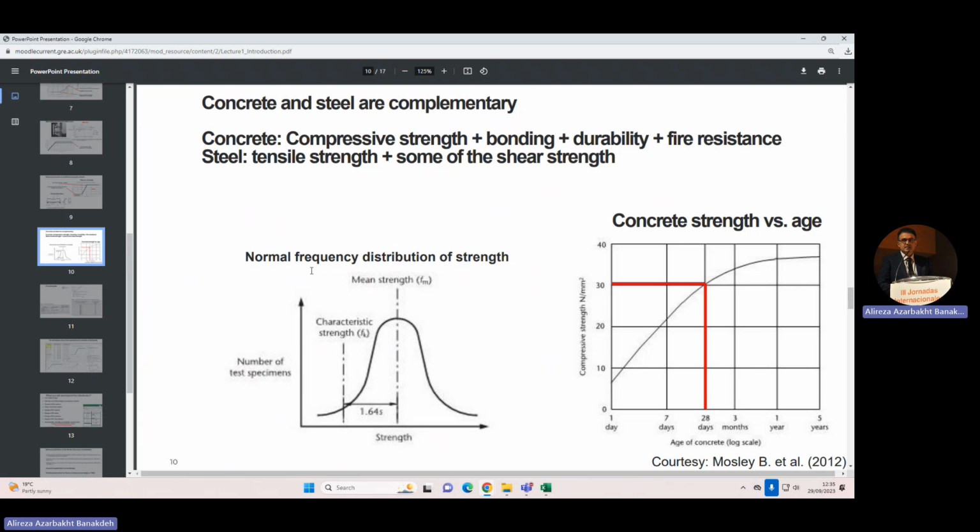We do not load a concrete structure before 28 days. Stand beside your creation and take your photos. You're a civil engineer. Do the right thing. Before 28 days, 1% is okay, but not 30% on a small bridge, it's a significant load on it. If you want to go alone, one or two people, that's fine, because that's a very small amount of load. But significantly loading a concrete structure before 28 days is not good.